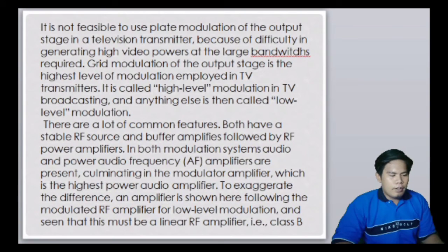There are a lot of common features. Both have a stable RF source and buffer amplifiers followed by RF amplifiers. In both modulation systems, audio and power audio frequency AF amplifiers are present, culminating in the modulator amplifier, which is a higher power audio amplifier.